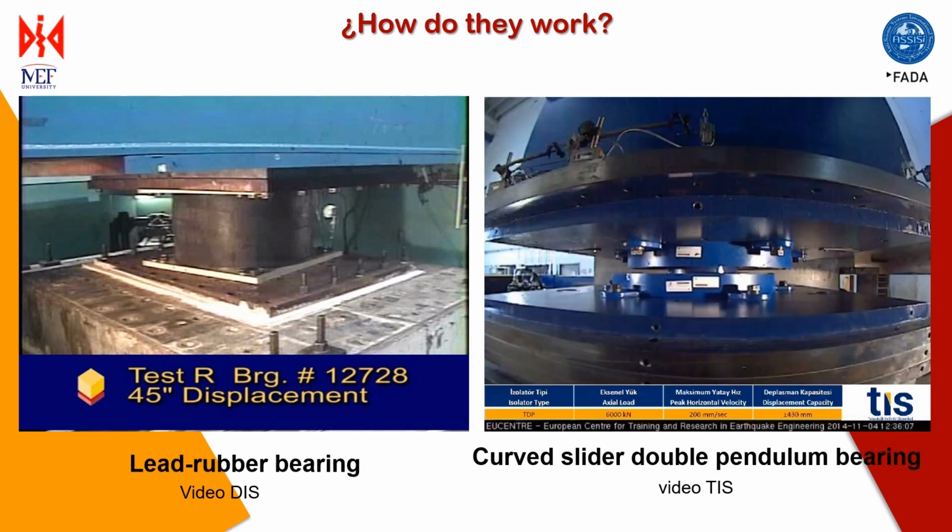The double friction pendulum seismic isolator works under the pendulum principle. This device allows horizontal displacement of the structure, providing the necessary change in its natural period when activated due to an earthquake. The important thing about the frictional pendulum, unlike the elastomeric one, is that it allows light structures to be seismically isolated.